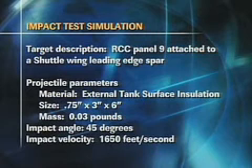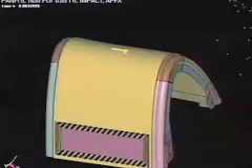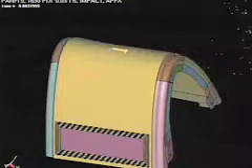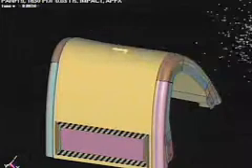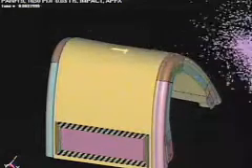This shows the impact of a 0.03 pound mass of foam at an impact angle of 45 degrees and about 1,700 feet per second. We show the video. It's a finite element code, finite element model. It shows the foam strike the apex. You notice the deflection of the apex during the impact. The yellow L shape there is actually showing that the model predicts a true failure of the panel at that location under these simulation conditions. What I'll be showing you next are videos of some actual tests that we've conducted with RCC. If you'll step to the next video.